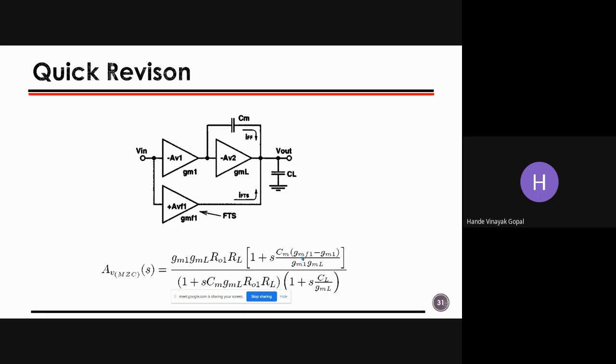In the resistor, the problem is the process variation. Because the resistor shows a lot of process variation compared to the transistor and capacitor, whatever compensation scheme you have implemented, you have to be very sure by running all the corner and mismatch analysis before proceeding, so that at the end you make sure that it works.